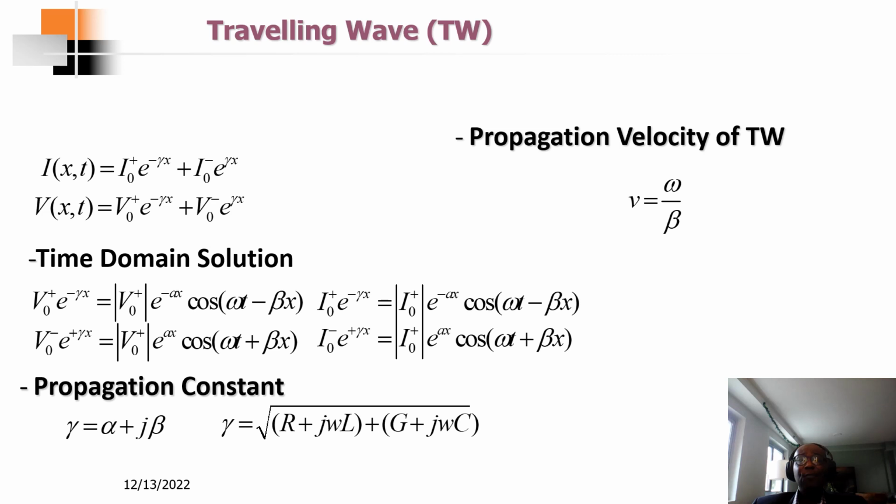So at the faulted point, these traveling waves are generated, and they move to each other end of the converter. The converter acts as an impedance for this traveling wave, where it gets reflected, refracted, and then goes back to the faulted point. So it goes back and forth until it is attenuated.